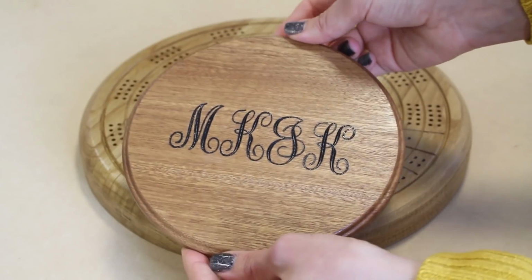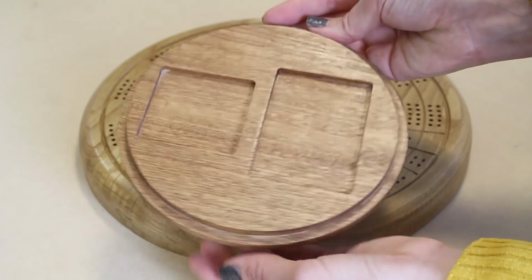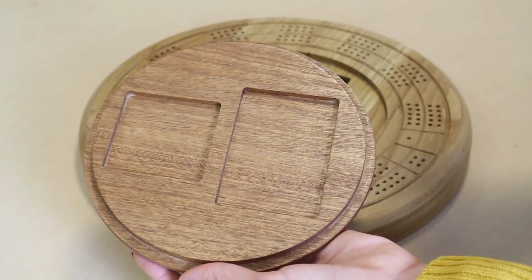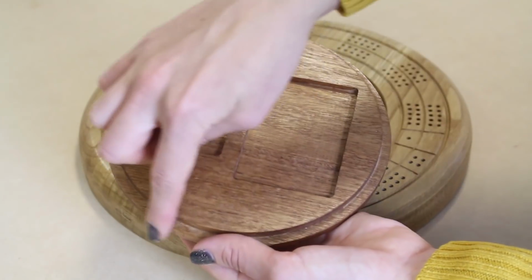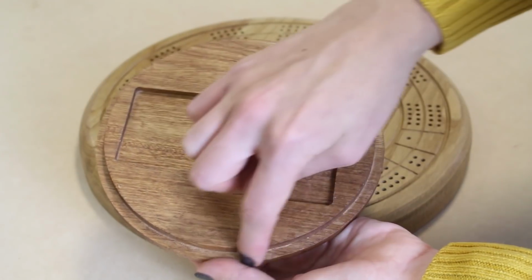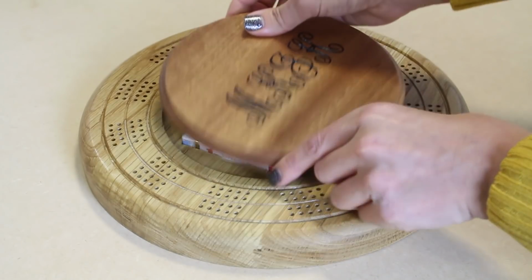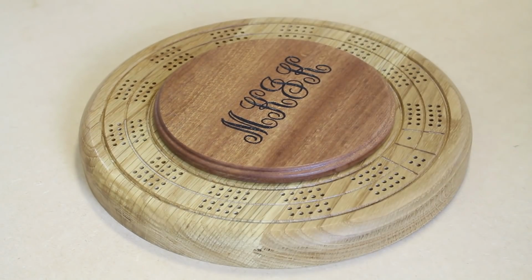This is a two-sided part, so on the bottom side we've got two pocket toolpaths for cavities for the cards and the pegs like you saw on the board, and then we have a pocket toolpath going around the edge of our part to create that gap where we can then simply insert that into the center of our board.